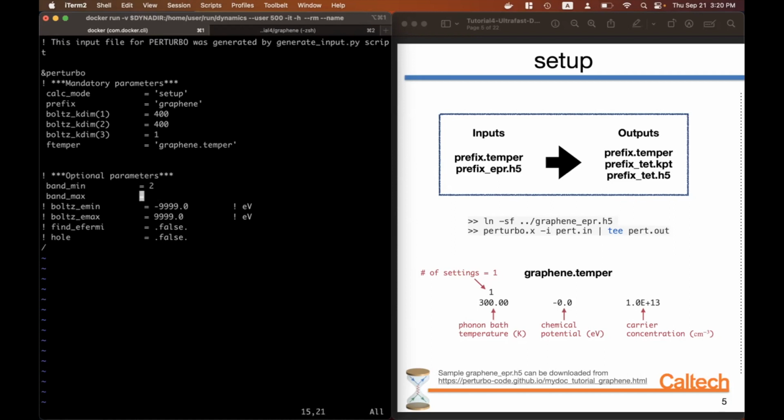So let's do 2. Emin and Emax should be chosen as desired, and I was previously saying that I wanted to set Emin to negative 4.93. As long as it's lower than the Fermi level, it's okay for this problem. And then for Emax, I need to set it to negative 3.5 in order for the results to converge.